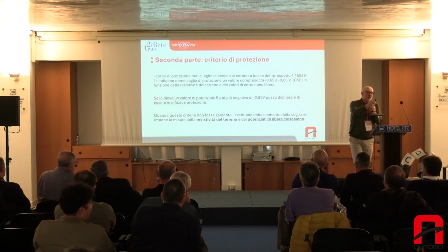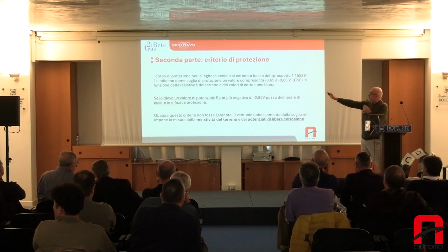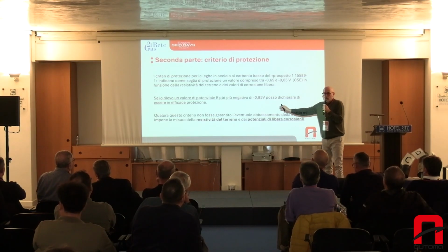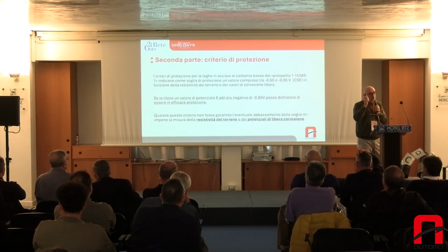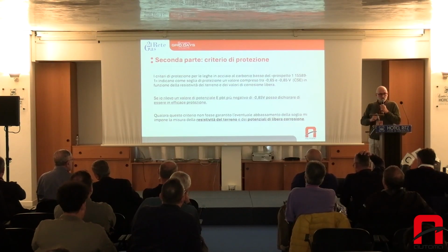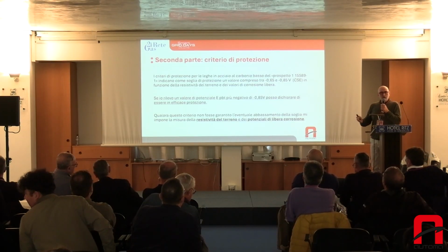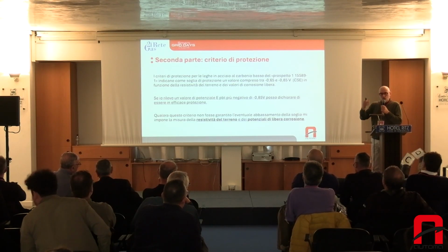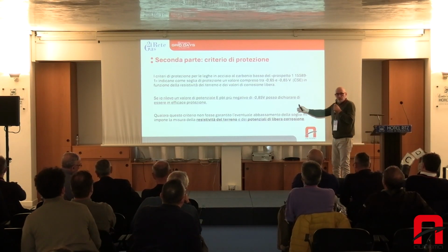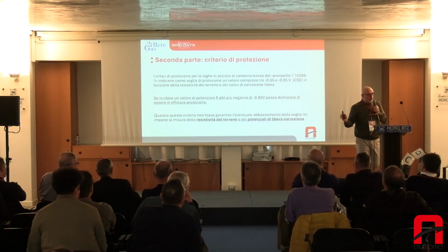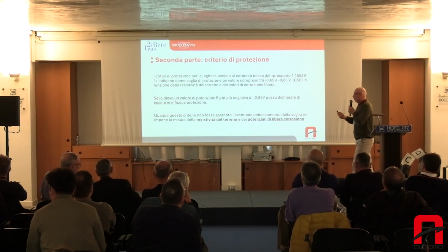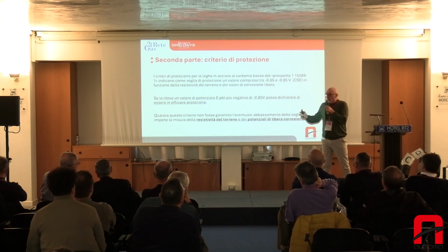Let's move on to the second part. I do my measurement and I read my potential minus 0.85. I'm okay, I'm protected, everything is okay. I'm not interested in the type of coupon that I used, where I placed it. I reach minus 0.85, I'm okay for 24 hours.